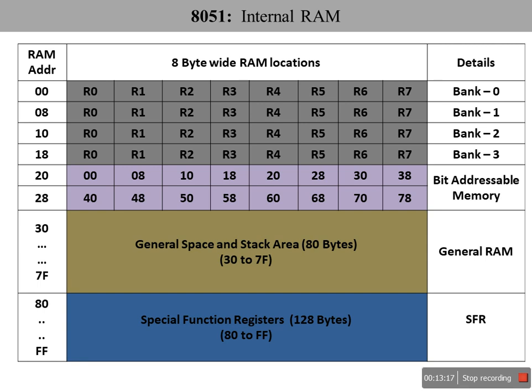Then what generally happens in regular programming? Each register may be dedicated to one fan. Then each register is capable of showing its status. Then in that case, what happens? R0 to R7 are dedicated to 8 fans. Then it will be around 8 bytes. 8 bytes of memory will be wasted. Whereas the same thing can be achieved using a single byte. The first bit represents the first fan, the second bit the second fan, and so on.